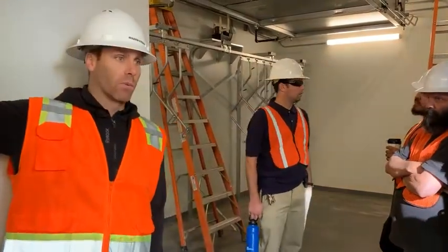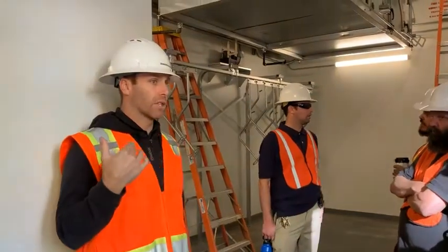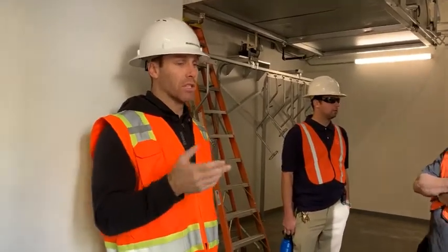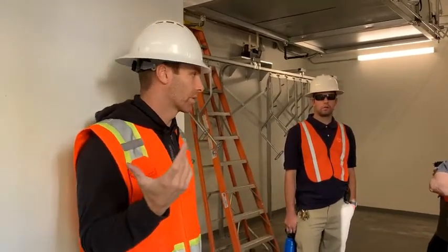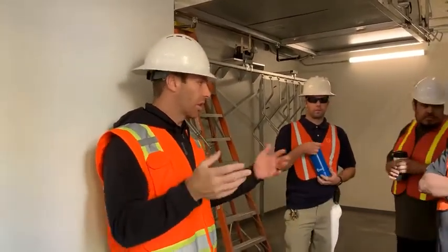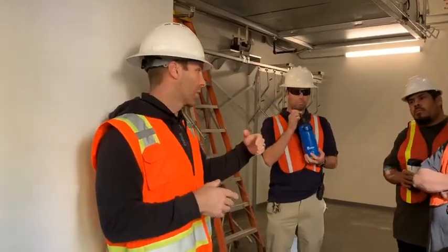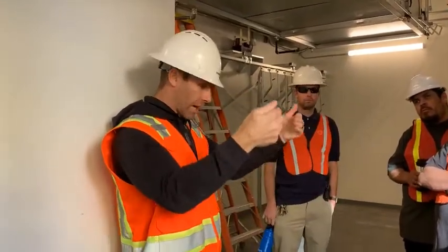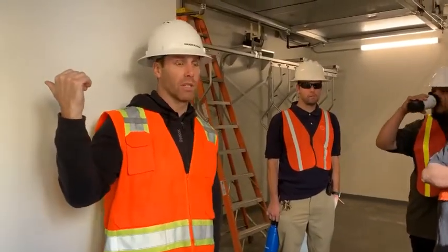So the Eclipse itself, up there, like I said, is the main hub. The way it communicates to everything, because it only has 2 Cat 5 ports but you may have hundreds of rooms, is bridges. Bridges are basically like an 8-port switch. Think of a server. They're just filtering all that information. So you have 6 or 7 rooms going back to a bridge, 6 or 7 rooms going back to another bridge. Those Cat 5 runs go to other bridges in order to get it down and down until you have usually one home run coming back to this Eclipse.